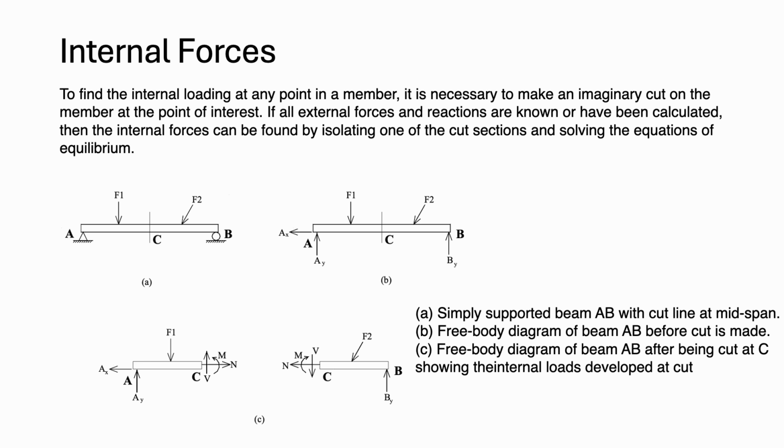Why do we need internal forces? Because this step is important to draw the shear and moment diagrams and the diagram of normal forces. And why is that important? Because we need to determine the maximum allowable stresses, which we will cover next time. So what we have here, figure A, is a simply supported beam subjected to two forces, F1 and F2.